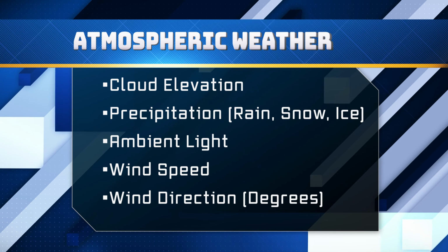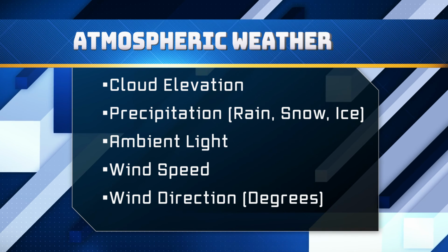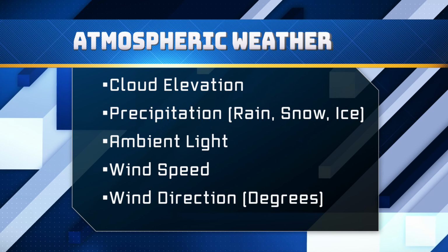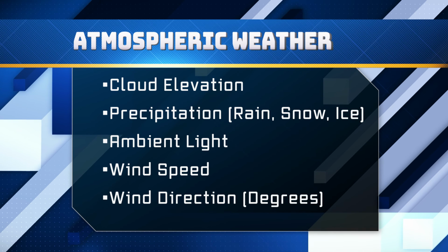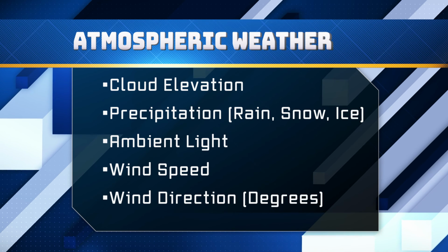You'll need to know the direction of the wind. And try to plan that toward the end of your flight, your return to home notification will be bringing you with the direction of the wind, because that will take less battery and will get you home faster than if you're going in the face of the wind.